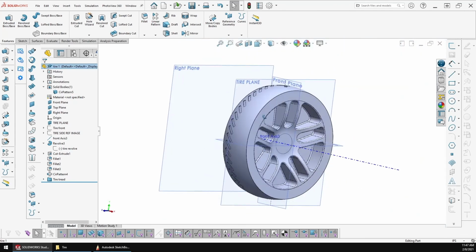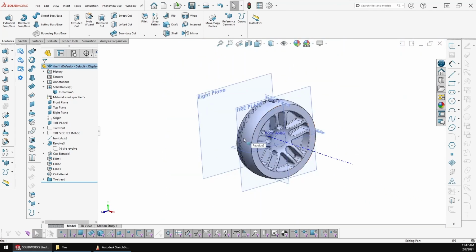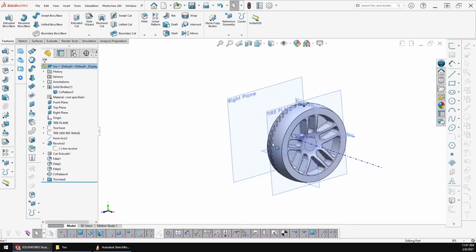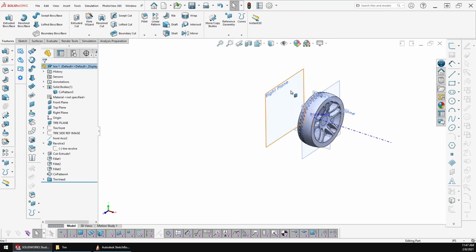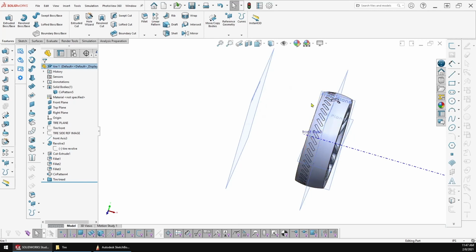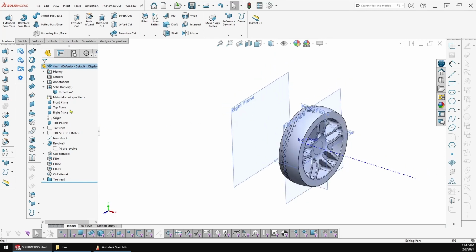So you can kind of see how our tire is starting to come together. Well, as mentioned before, we want to use these tires to get our proportions for our body correct. Now, we haven't sketched out the profiles for the body yet. So we're going to use these tires as an underlay to get the proportions right. We know that the width of our tires, we've already determined, was 12 inches. So what we can do is just come in and offset it.